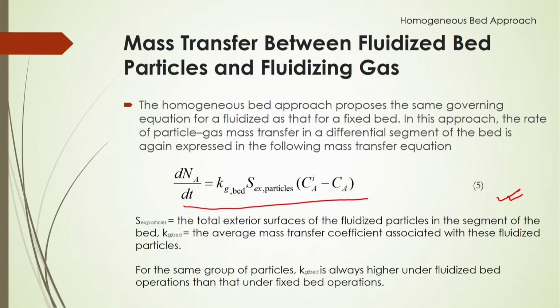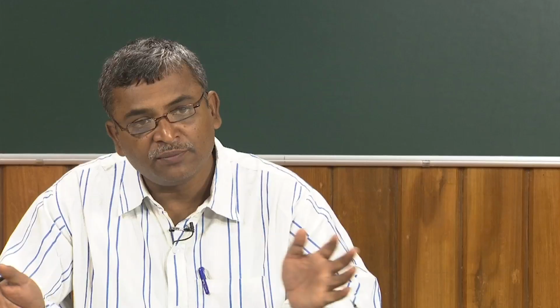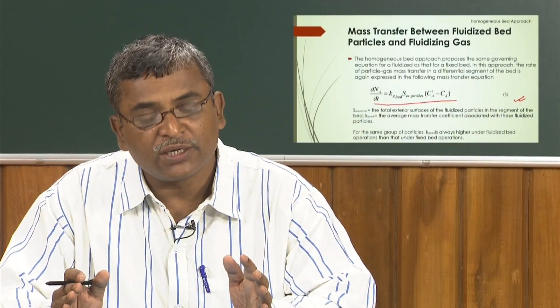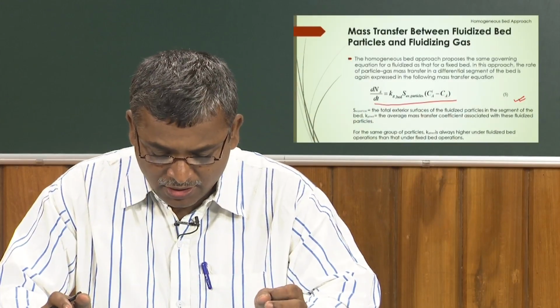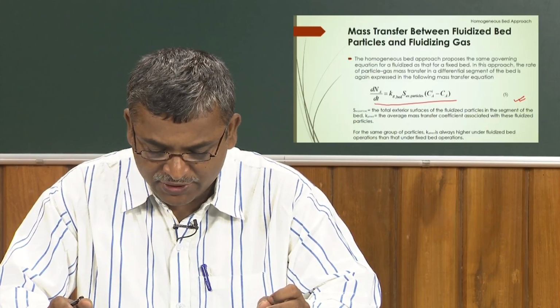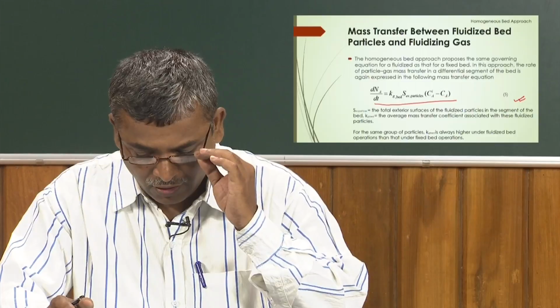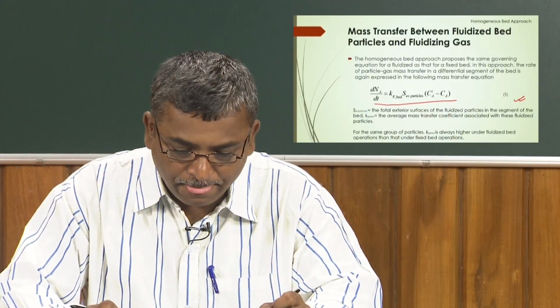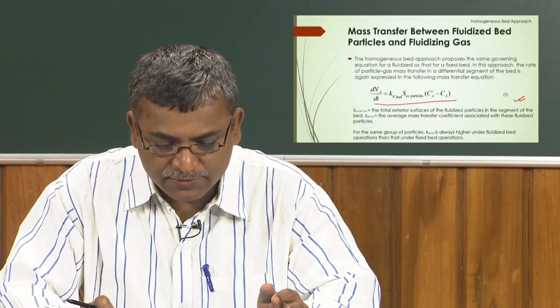If you are using the same group of particles in fluidized bed operation and fixed bed operation, and you compare the mass transfer, you will see that for the same group of particles the mass transfer coefficient in the bed will always be higher under fluidized bed operation compared to fixed bed operation.